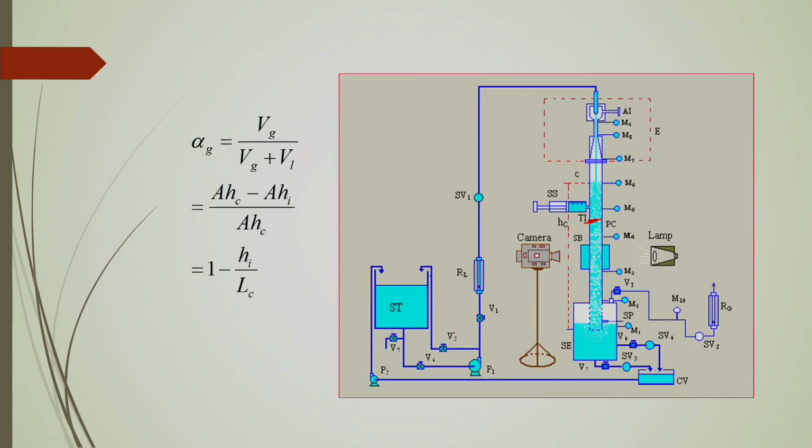Okay, now if you allow that liquid jet to be plunged on this pool of the liquid, you will see the gas will be entrained, and accordingly after entraining that gas, the mixture volume of this gas and liquid will increase and it will go up to a certain level. So, up to this is called the mixture volume. This mixture volume will come at a certain gas and liquid operational velocity or flow rate. So, in that case you will see that the gas liquid mixture will be coming up to a certain height of this column.